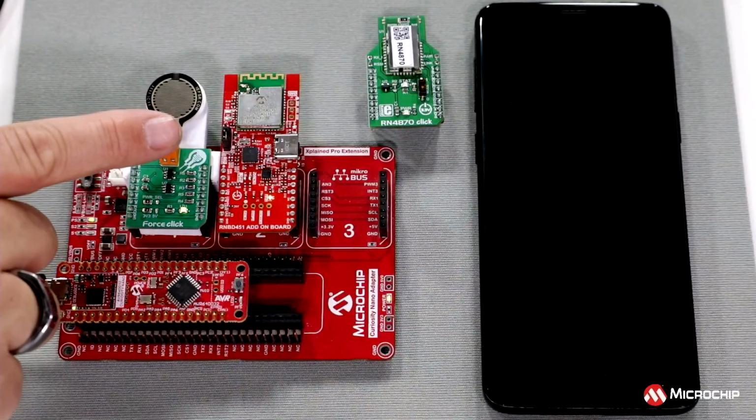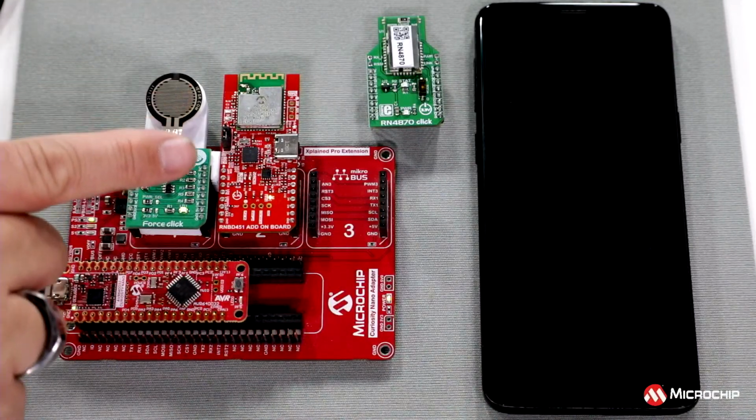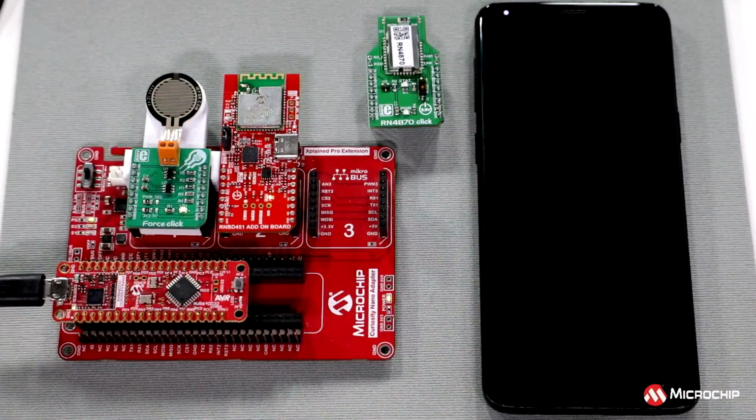Gotcha, thank you. This next question is for Ross in regards to your demo. This person's asking, when working with the newer RN-BD451 versus the older RN4870, what changes did you need to make for the project to work? So the only change I needed to make was to change this jumper from USB to being powered by the board, and that was it. The baud rate is the same, the frame format was the same, it's a USART connection, so it's just TX and RX, there's no flow control, and it just works.